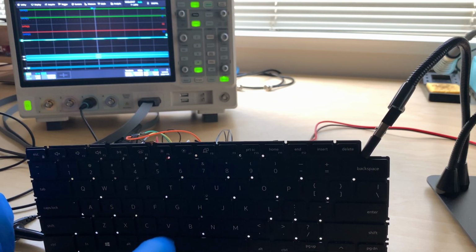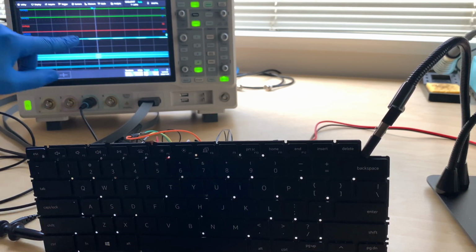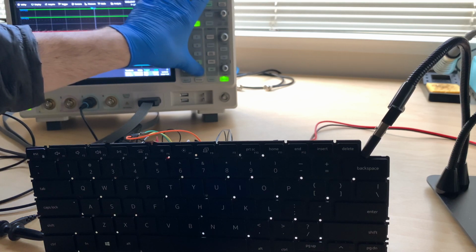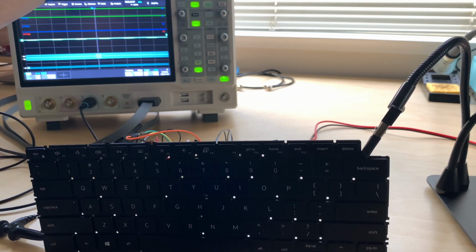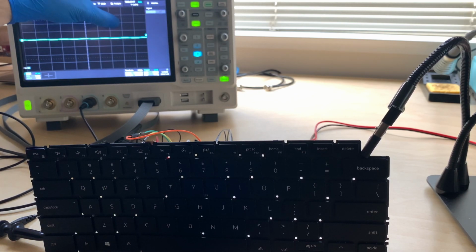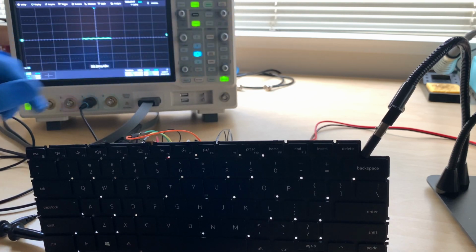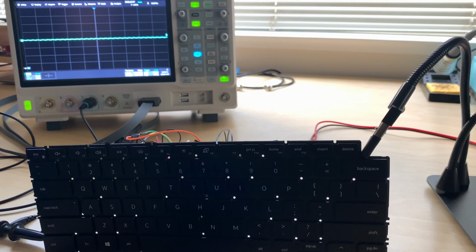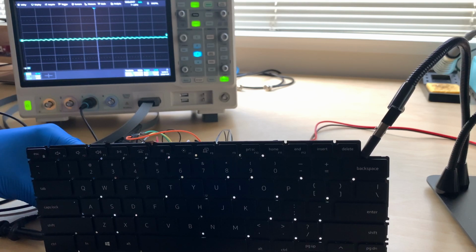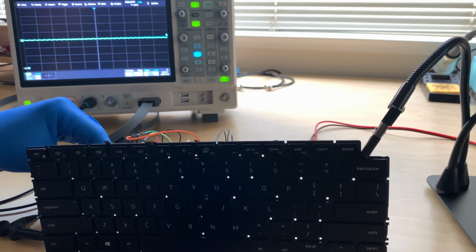So the matrix scanning algorithm solves this by organizing the keyboard into a grid, and whenever a key is pressed, one of the row inputs is pulled high, which might be the rows, and then we can scan each column, testing whether we can pull that column high. If we can, then we know which column and which row has been depressed, telling us which key was selected. It's not a much more complicated algorithm, but there are a number of edge cases that we need to consider.